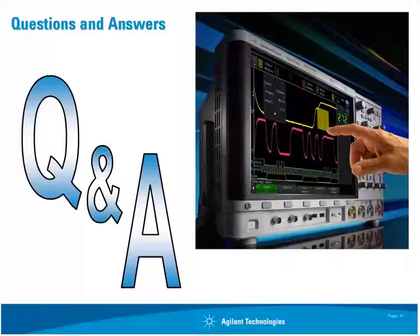If a scope has a fast waveform update rate, it's going to pick up those extremes extremely fast, whereas a scope with a slow update rate is not going to show you those extremes. So if you don't want to see the noise that's really there, you can use a method I talked about earlier of intentionally slowing down your scope's waveform update rate. But in my opinion, I want to see what's there, even if it's extremes that are not pleasing to the eye. At least it's showing me what's really there. The scopes that are updating slower are masking or hiding what's really there.